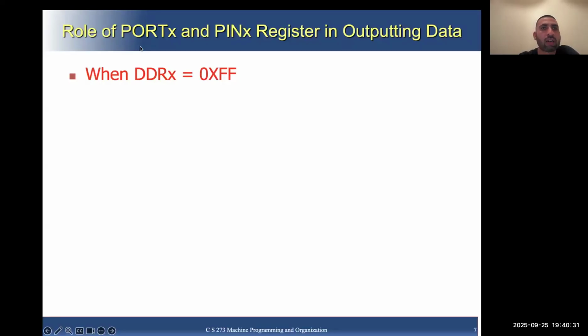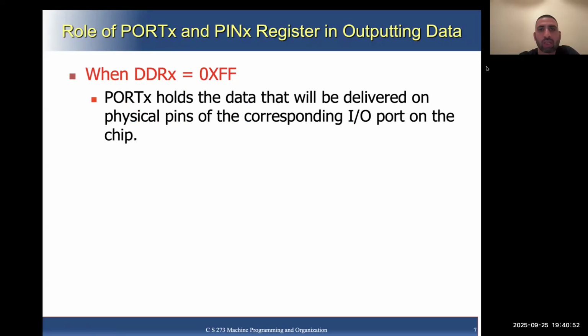But we have not discussed the PORTx and PINx registers in detail. Actually, we have not used the PINx register at all before, but we have used the PORTx registers, like PORTB or PORTC, but we haven't discussed some other functionalities of that register. So PORTx is used to hold the data.